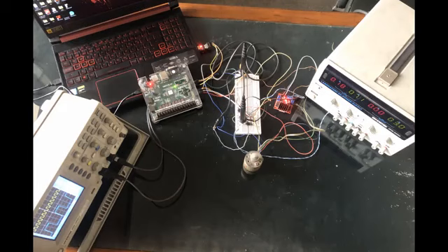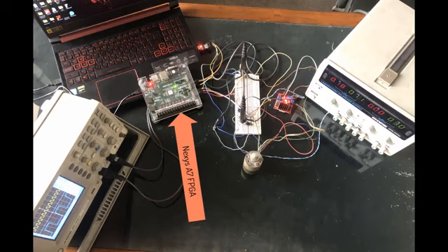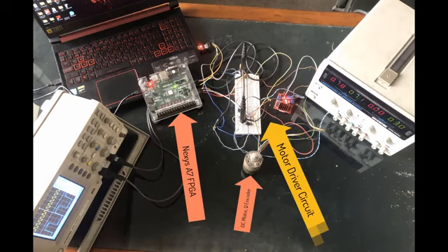Here is our complete setup. We have compiled the high-level program of motor control into RISC-V machine code and dumped it into the instruction memory of the SoC. Then the Nexys A7 FPGA board is programmed with the bitstream of the SoC. We have the DC motor along with the quadrature encoder. There is a circuit which consists of the L298 motor driver and the optocouplers. Then we have the variable DC power supply to vary the speed of the motor by changing its input voltage.